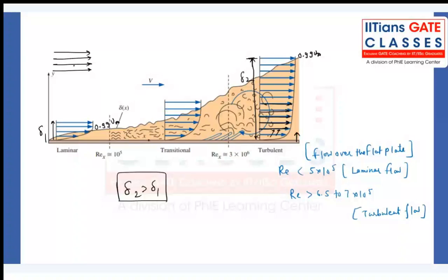Hardly any communication will be there, but still some communication will be there because of the property called viscosity, right? This fluid layer will say, I'm being slowed down. The second will say, okay, and they will offer some kind of resistance. It will also slow down, and slowly they will start gaining velocity up to 99% of the free stream conditions. But in turbulent flow, what is happening?